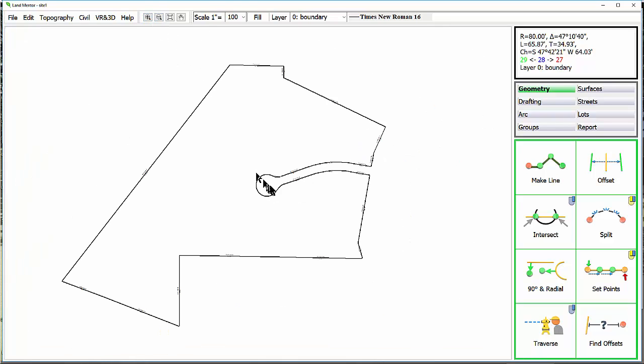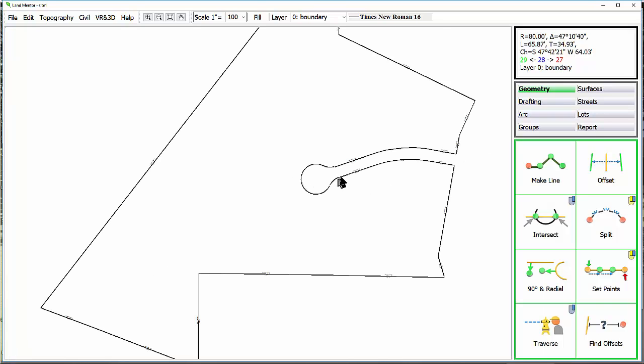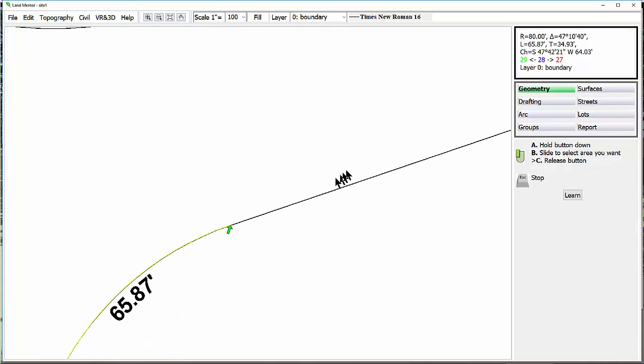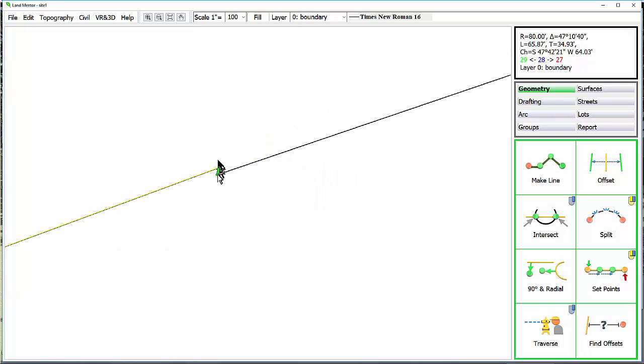But it doesn't close really because of the rounding of angles and distances. The site actually won't close. So if you could see, I start off with this line and it went around, so point 1 to 2, and then it ends with a point 29. If it closed, 1 would equal 29. Because there's a little bit of error when you're entering this data where you can see that it doesn't close. So you really have to force a closure.